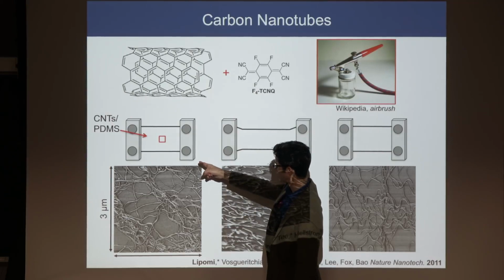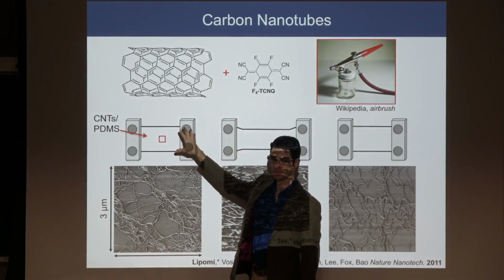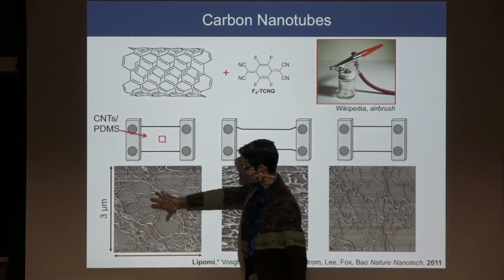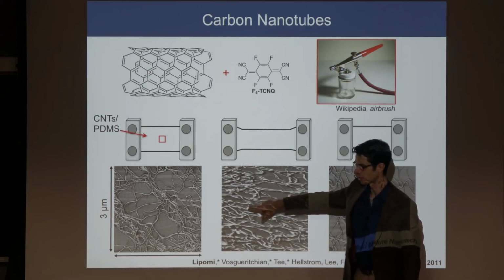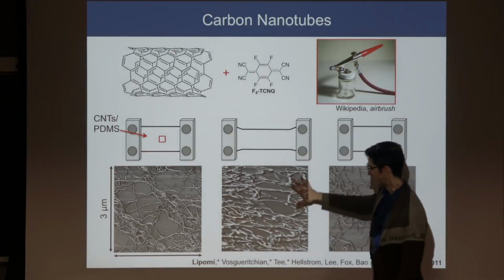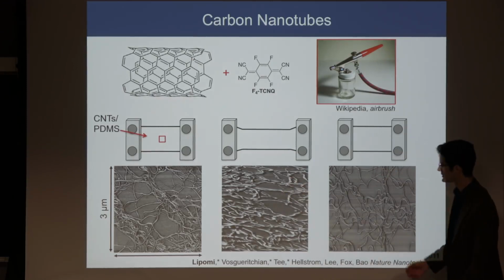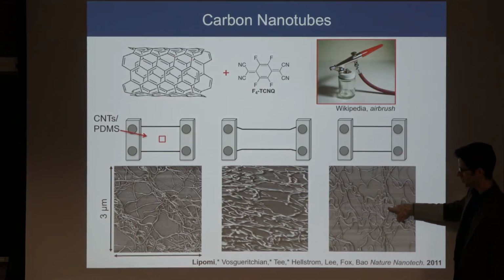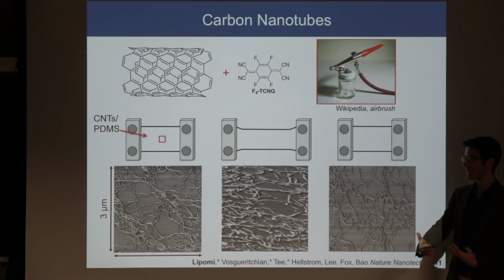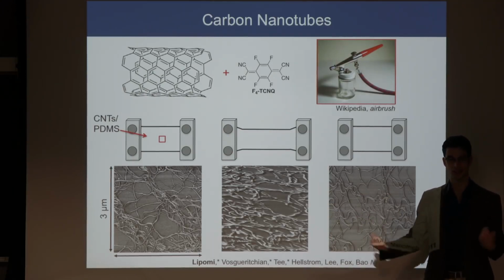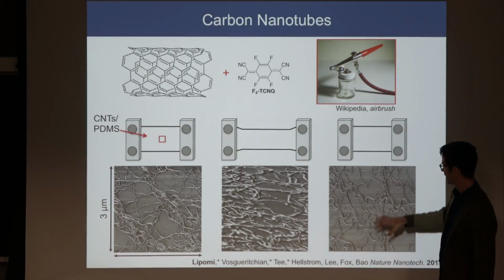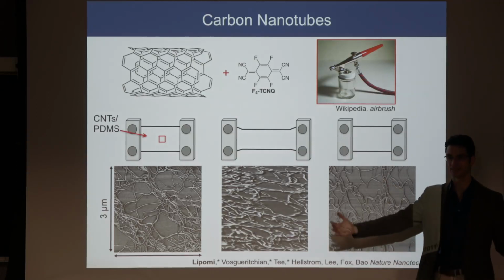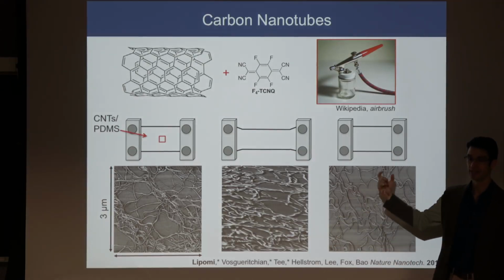So the idea here was to make a carbon nanotube film that was reversibly stretchable. So you stretch it out and you stretch these anisotropic nanotubes into this in situ stretched image, and these are atomic force micrographs of these carbon nanotube bundles. And then when you release the strain, these carbon nanotubes are buckled, but they're primarily buckled along the axis that was strained and then released. Because of this effect, you can restrain these carbon nanotubes by stretching them out, and then they fold back up, stretch them out, they fold back up. And because they're like this, they can now accommodate that strain without breaking connections in between the nanotubes.